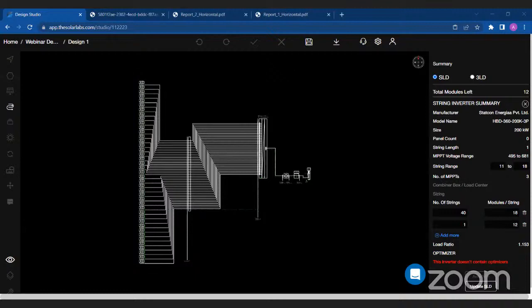Regarding that, I think there is a 3 to 4% variation in the generation number between PVSyst and Solar Labs. Solar Labs tends to show a lower value than PVSyst. Right. So by the default losses parameter, yes.